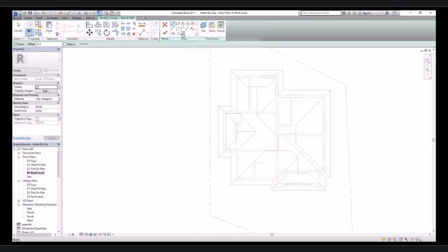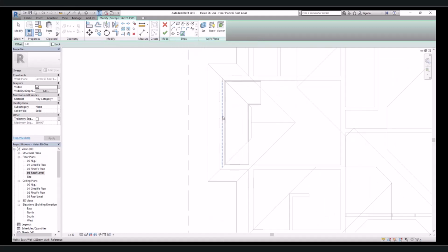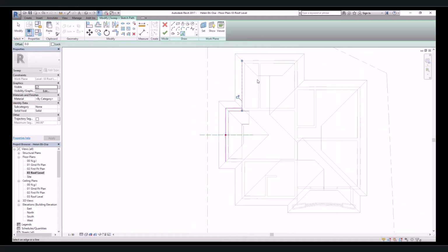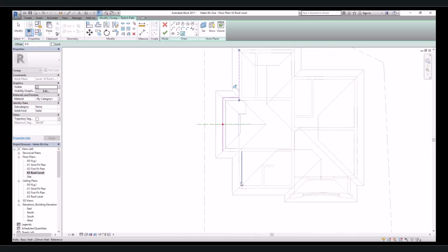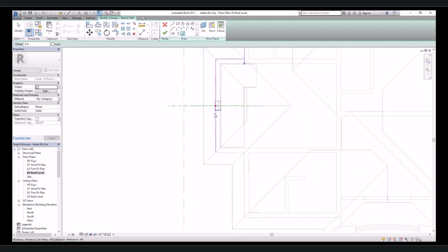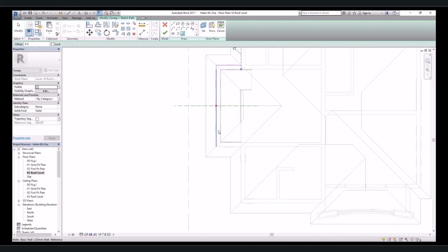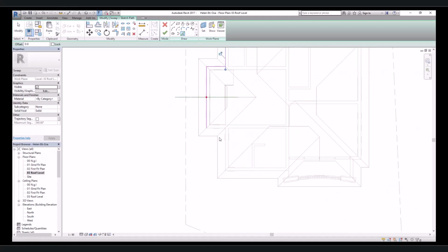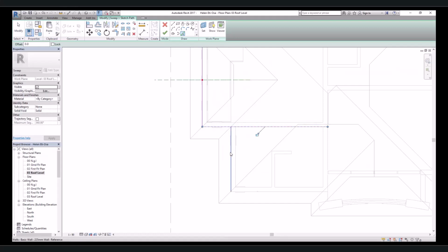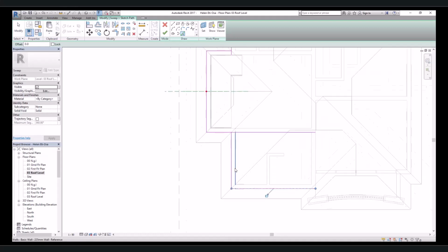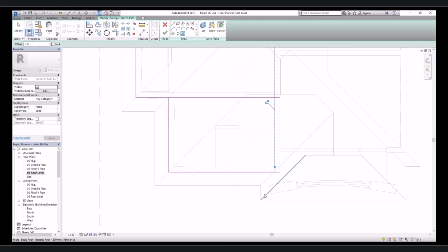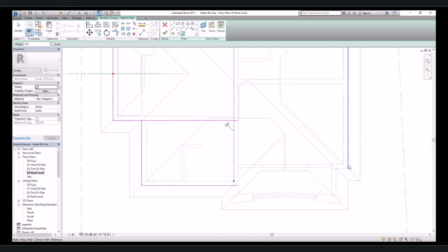When you click on that, it will bring you to the drawing mode here, and you click Pick Lines, and you can just pick all the lines. Please note that I'm really mindful of where I drop my first line. I deliberately drop it here because it will be convenient for me to draw the profile from this side.